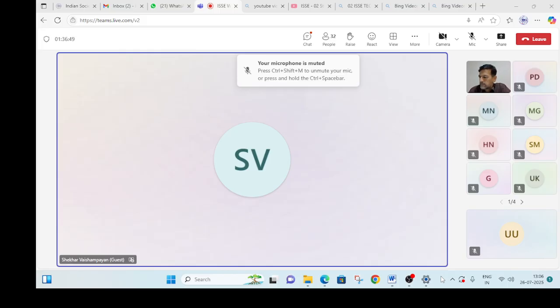So Shailesh would probably know that when the load passes from the column to the piles, it doesn't carry the moments because the pile caps are very rigid. Only the lateral loads and vertical loads will pass through, and the moment induced by the lateral loads acting on the top of the pile cap will be there.